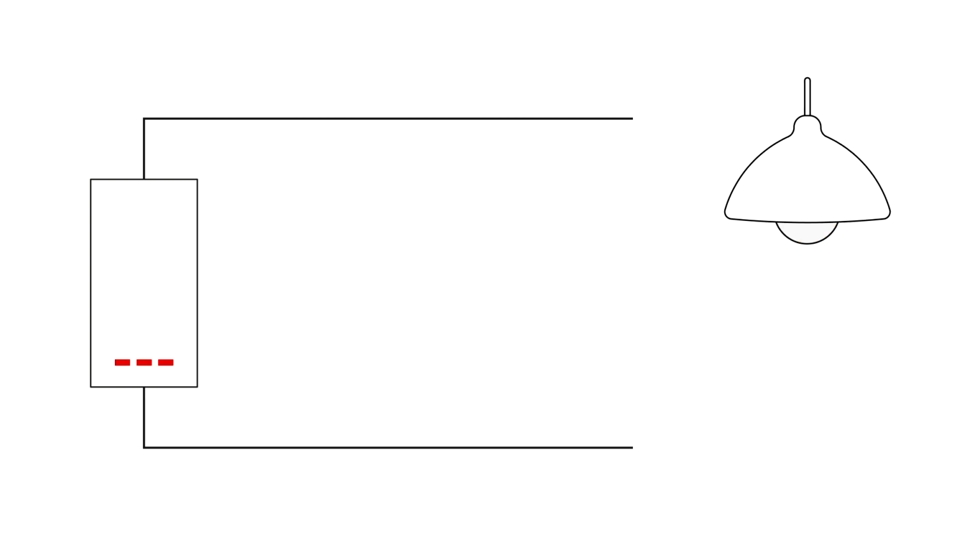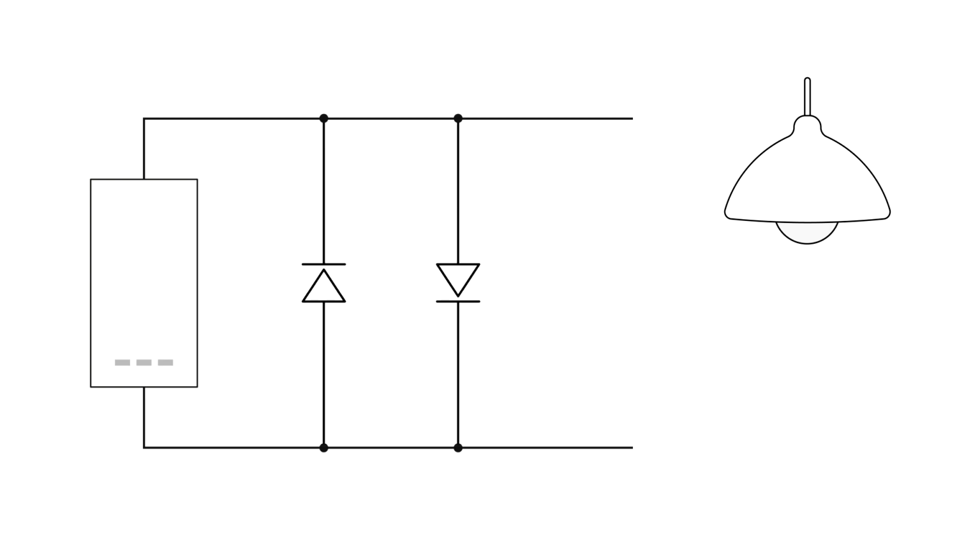The backlight LEDs are connected in parallel and are combined with the button contacts, so a backlit button uses 2 wires for connection and occupies 2 input channels. Not all modules support the connection of backlit buttons. See module descriptions. In most cases, the built-in backlighting of buttons is designed for 24 or 220 volts and requires modification to work with our equipment.